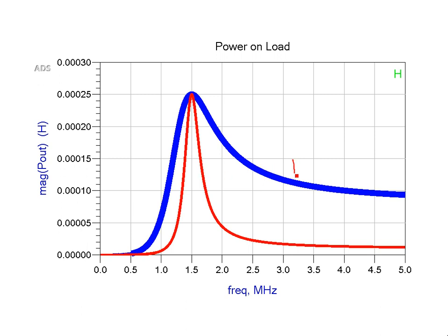Okay, so this thick blue curve is for my RL equal to 100 ohms. RS is the same. We are just considering the effect of increasing the load resistance on the bandwidth of the match. So my RS is set to 1000 ohms all the time, and I'm just increasing my load resistance. This bottom curve is for RL equal to 10 ohms. And if you recall, the quality factor for this red curve at the match was about equal to 9.95,